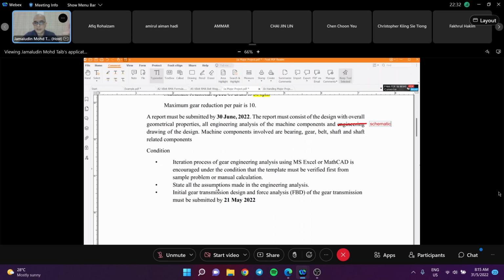You check the interference. After that, you check the bending stress against fatigue. Then you check the surface stress against surface fatigue. Whether it's going to fail at the end doesn't matter. That's fine, not to worry.